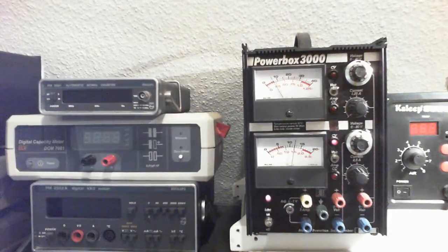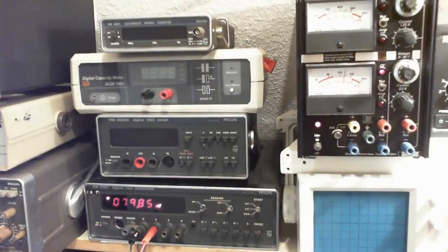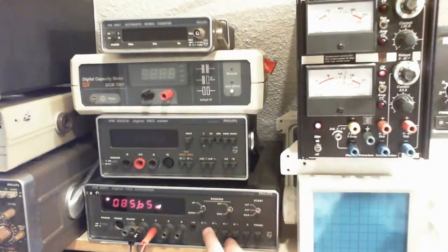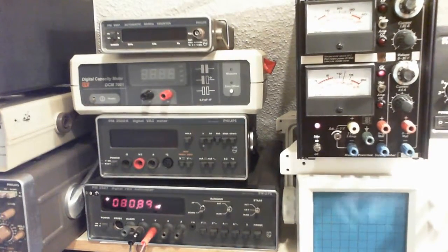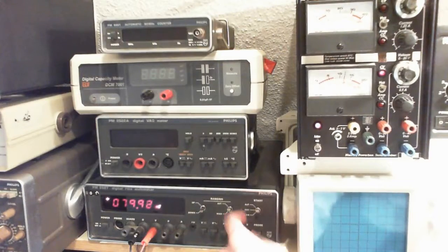So there are other ways to measure voltage. For example, you can use voltmeters. Now, for example, this multimeter over here, with this you can measure direct current, or volt DC, volt AC. This is alternating current, and this is amps DC, amps AC, and ohm. So with these two you can measure current. With these two you can measure voltage, DC and AC, and this is ohm, which is basically resistance.